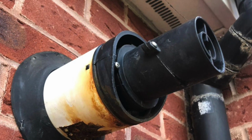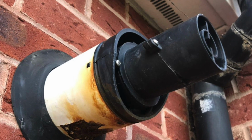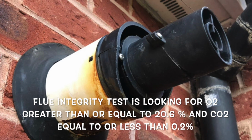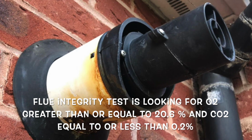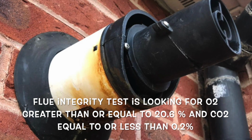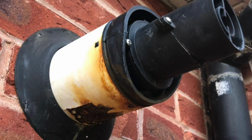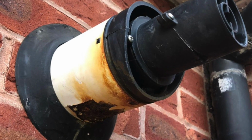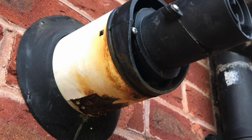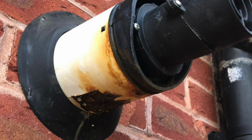So when you do your visual inspections of the flue system outside, you find this. But when you do your flue integrity test, the integrity test fails. But when you do your sweep test around the flue system and the turret and around the boiler casing, it passes. So you do not have more than 10 parts per million CO coming into the room. So how are you going to categorise this?